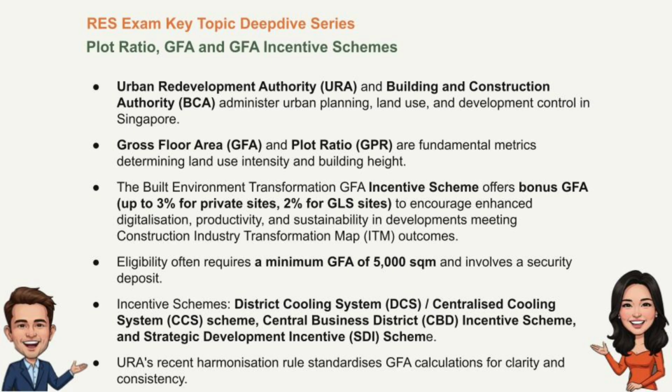The real-world constraints. This is a crucial caveat, especially for anyone assessing development potential. The answer is no. You can't always achieve the maximum theoretical potential. Why not? What gets in the way? Various practical and regulatory factors. A classic example in Singapore is height restrictions near airports and air bases. Right. Paya Lebar, Seletar, Changi. Exactly. Developments in those areas often have much lower allowable building heights and sometimes lower effective plot ratios because of airspace safety requirements, regardless of what the base master plan GPR might suggest.